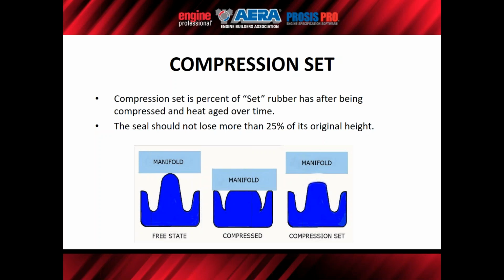When I worked at Felpro and we did the compression set testing, we saw that some of our offshore suppliers had compression sets that were higher than 30 to 40%. And that just tells us that the particular compound that they had was filled with ash or some other kind of filler that didn't have the properties that were significant enough to prevent the compression set. So you may save money buying a cheaper set somewhere, but like I said, you get what you pay for.